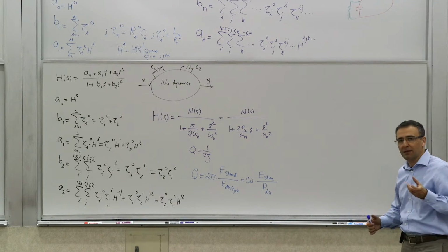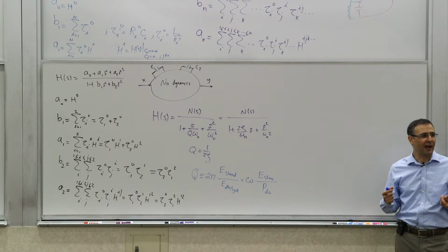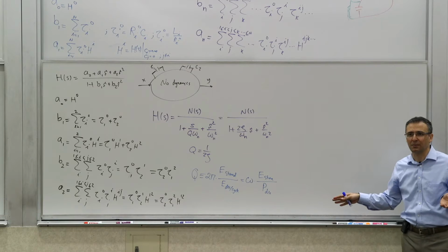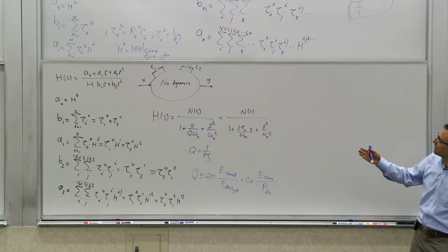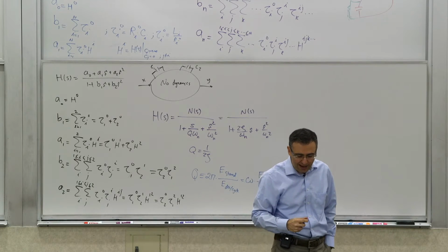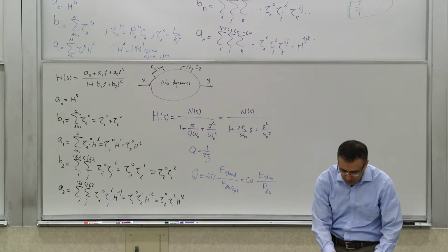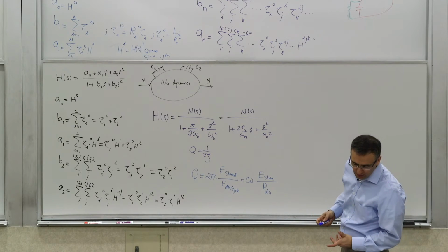So that's a measure of how resonant something is, right? The higher the quality factor, the more cycles it takes for the energy to get dissipated. So this is a metric that usually shows what the transfer function of the system looks like. And natural frequency is also a useful thing to know, because it shows you where the natural frequency of the circuit is.